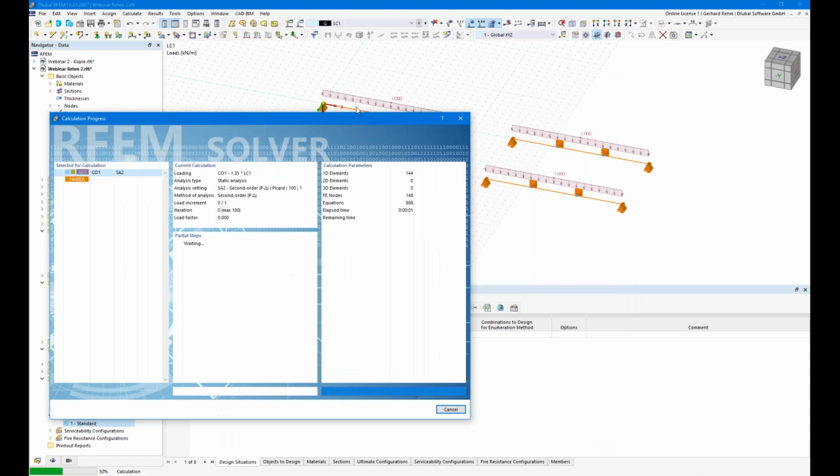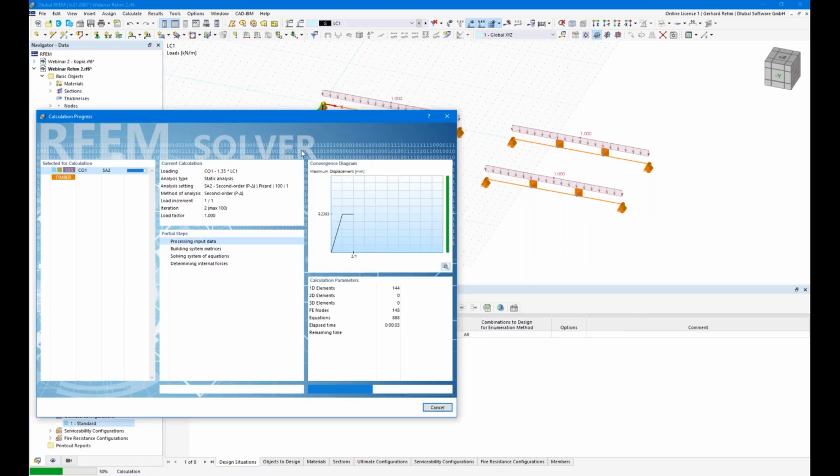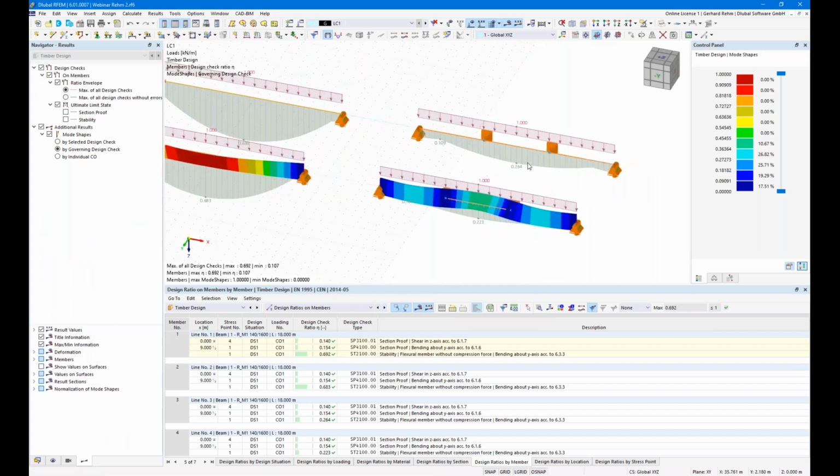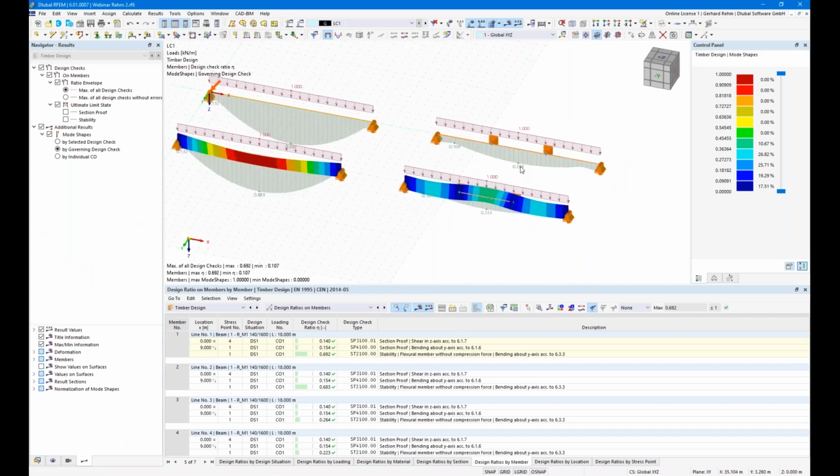Of course, the ratio must be smaller now than the ratio from the left side. So yeah, the ratio goes down to 26 by the analytical solution, and the eigenvalue method here. The difference is a bit more now compared to the left side, of course, because the assumption that there's a constant moment distribution is not completely true, because it's not really constant. And of course there's a difference.